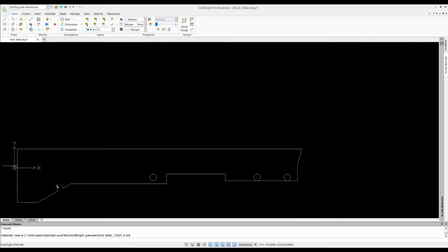I'm almost second guessing whether we should have made this a little bigger, just in case the part doesn't exactly line up where we want it, so we're not covering our hole. So I'm going to go ahead and do that. If you want to snap a hole right in the middle, you'll have to find an edge there and then center a line up so it'll snap. So you can do a new hole. Let's make that one 2.5 inches.